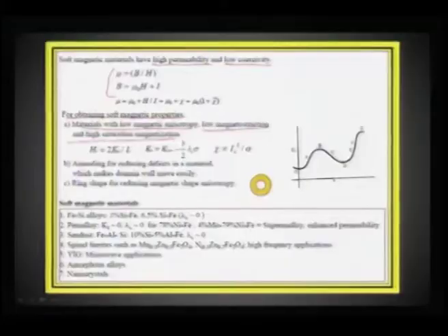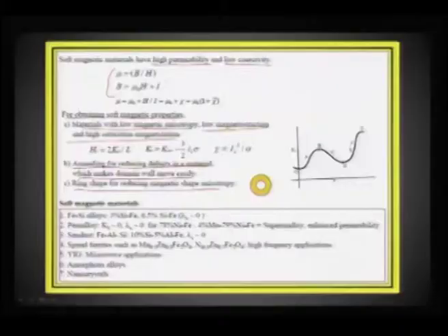And how do we get these soft magnetic materials? We can engineer it by carefully annealing in a furnace or with other annealing protocols, where we try to minimize the defects, which can help the domain walls to move easily, so that we can get this response. Another way to get a soft magnetic response is to make a ring shape, so that you can minimize the shape anisotropy, because shape anisotropy can influence your magnetocrystalline anisotropy. As a result, if you make a ring shaped one, you can considerably minimize the magnetic shape anisotropy.